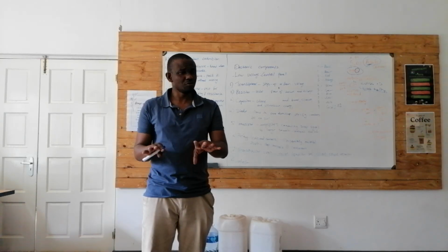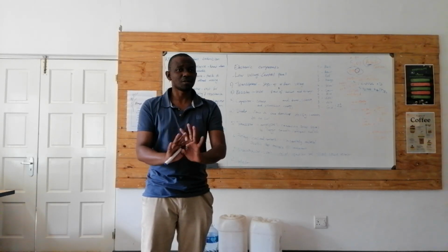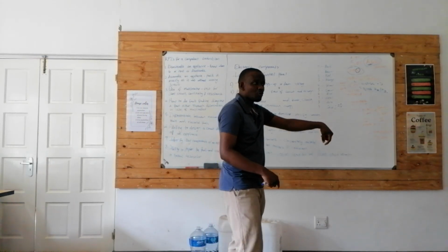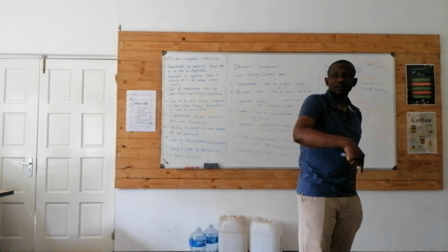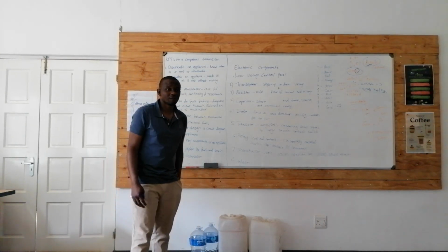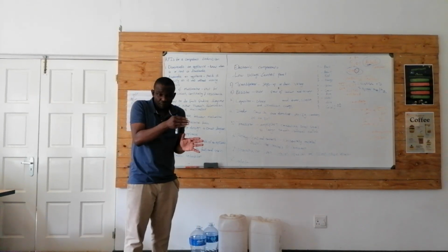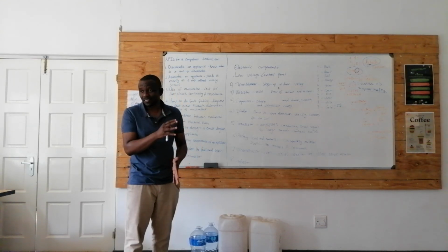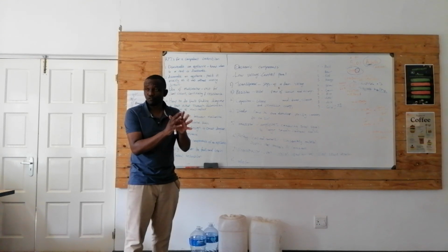You check the fuse is right. Every component of the power supply is fine. You trace, you can see that the current is actually flowing and it goes to the control panel, but from the control panel, there's no power at all. Which means the power can flow in, there's nothing wrong on the power supply. But on the control panel, that's where you need to focus.